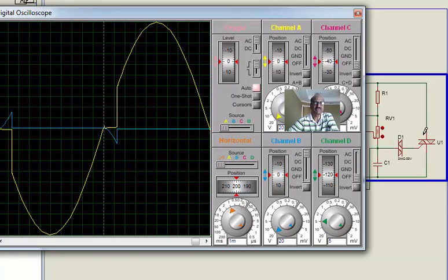which are a matter of more theoretical subject, where the gate requires more current as compared to the first quadrant. In the first quadrant and third quadrant the current requirement in the gate is less, whereas in the second and the fourth the gate current requirement is high. Those are all a matter of a little more theory. We will not go into more details of that.